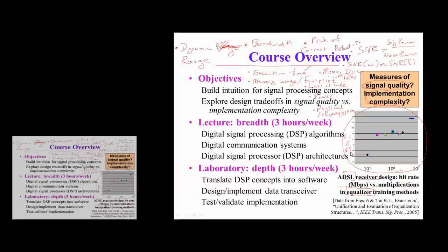Farthest right? So in fact, they give all about the same data rate. They're all about 6.2 megabits per second. And this one you want to eliminate, which makes sense to me. It's more than 10 times the complexity, and I'm really not getting very much improvement in the signal quality in terms of bit rate. So why would I spend all this extra effort for such a marginal improvement? And I can apply the same idea, get rid of all those. So now I'm down to 3 choices that are practical. I have a low data rate, low complexity, a medium data rate, medium complexity, high data rate, high complexity. 3 reasonable choices, 3 good design points to choose from in my final design.